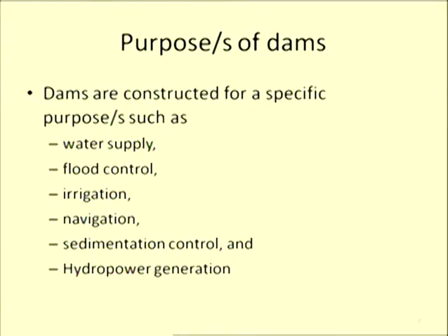One more objective is the control of sedimentation. What is sedimentation? Soil gets eroded during rainfall. When rain falls, the soft particles of the soil in the field or in the forest get eroded and flow with water. They settle down when the velocity of flow reduces, and get deposited, sometimes in a structure and sometimes where there is lesser velocity in the channel.